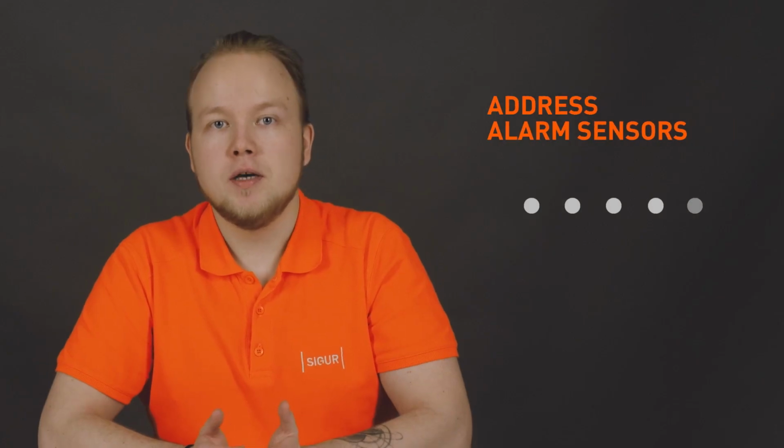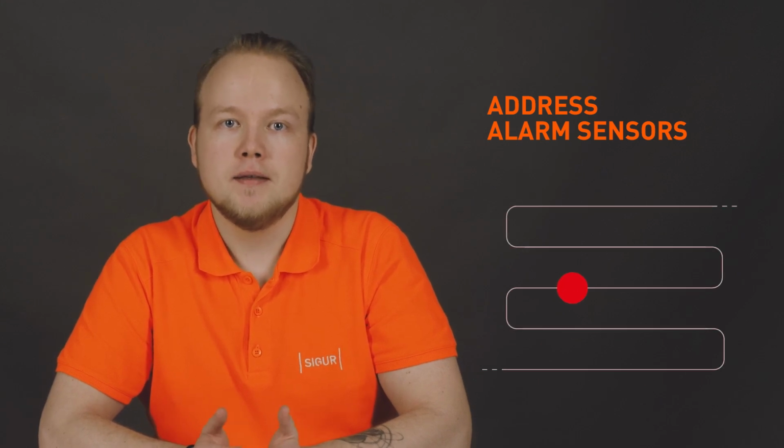However, as a rule, they are all united by two types of information transmission: addressable and non-addressable, also known as analog. Addressable sensors allow you to understand which specific sensor installed in the room has been triggered. For example, in large warehouse spaces where the number of sensors can be counted in dozens, an addressable device allows for a higher level of information and data reliability.